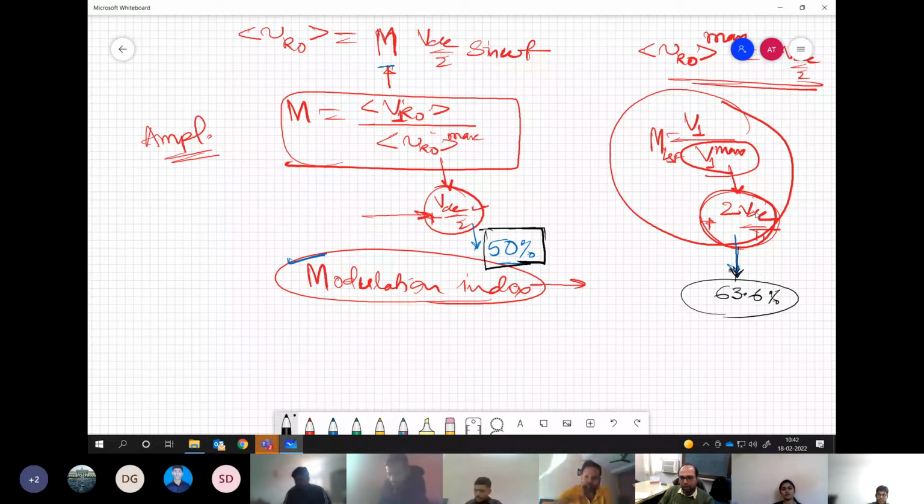So you clearly see that there is some difference, no? Almost 13% difference if you see with respect to this. So always our reference point should be fixed first while talking about percentage. So with respect to the low switching frequency PWM or square wave, we have 13% reduction in the DC bus utilization.